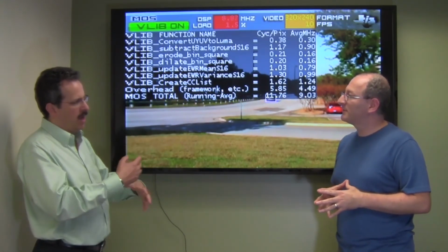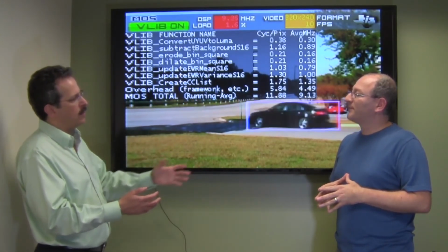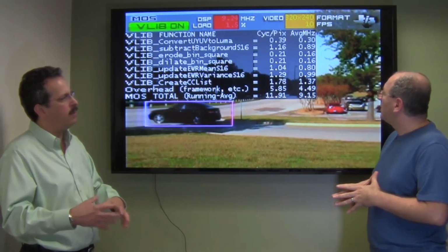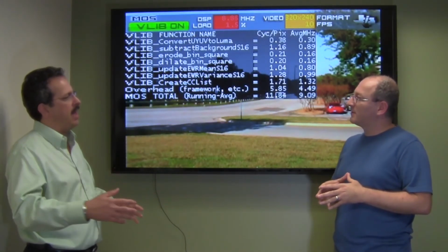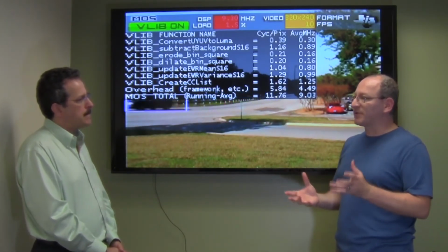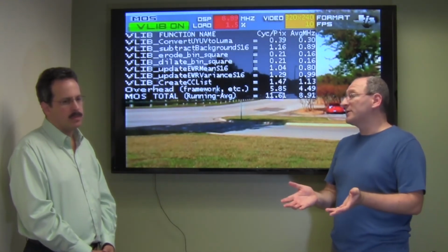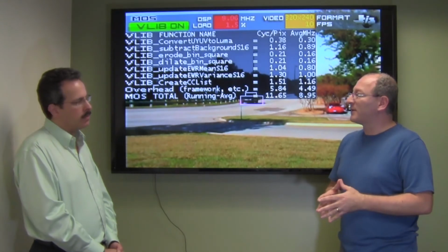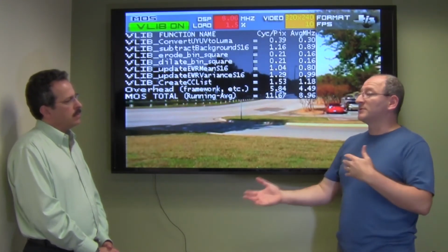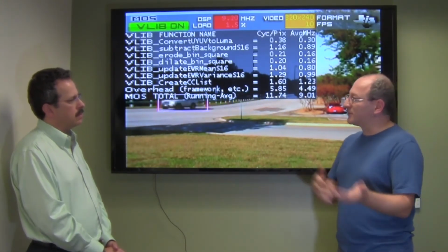Exactly. And optimizing the flow of the data through memory, so we're minimizing the shuttling back and forth, doing everything we can on a chunk of data while it's in level 1 memory. Exactly. There are two aspects of this full application flow story. There is the compute part, which is relatively easy to quantify: how long did it take for these pixels to be produced? And there's also the I/O, input/output: how much time did I spend bringing data into my memory?